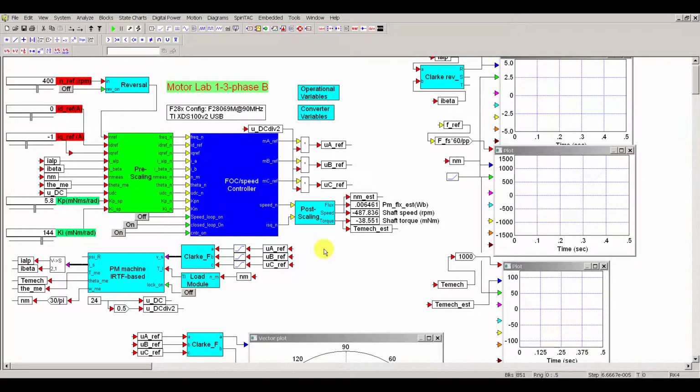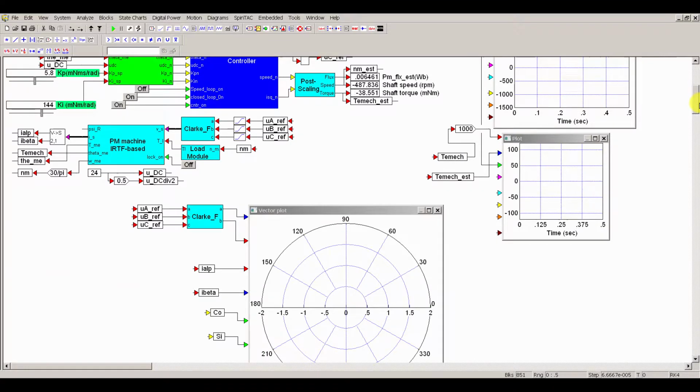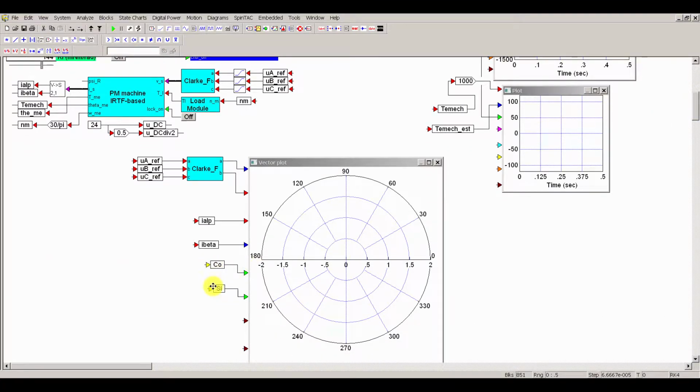So we need to orientate ourselves. We can do either speed control or we can do current control or closed loop control. So we'll do this with just current control right now, and that's probably the easiest. And we're going to observe, of all things, this vector. Now the d-axis is automatically set in the same direction as the flux.